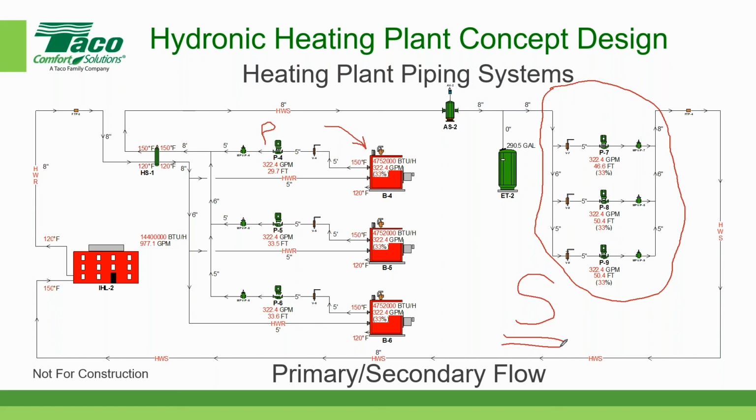And so now the only reason that you would have minimum flow on the secondary side is typically to protect the pump. If you had minimum flow requirements on the primary side, that's typically to protect the boiler. Generally, in the primary side of the system, the boiler determines what the minimum flow would be and not the pump. In the secondary, generally the terminal devices don't really care about minimum flow. They certainly would care in terms of capacity, but not in terms of operational characteristics. And so the limiter on the primary, secondary side would be the pumps themselves.